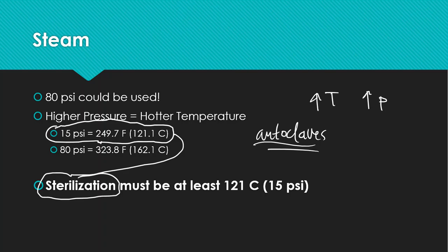So these autoclaves or the sterilization process that you will do on the manufacturing line both require a couple of things. Number one, we need to make sure that we go to 121 degrees Celsius, and that pressure should be around 15 psi. If it is, then that means that my autoclave is working the proper way, or my sterilization technique is going the proper way.